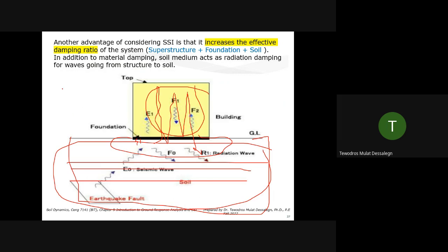And the other thing, actually, the Nuclear Regulatory Commission forces us, because in case there is a resonance in the soil, you can only see it, that resonance, that amplification being introduced into the structure. Sometimes what people do is they analyze the soil alone and use that output directly for the structure. No. You can do that kind of approximation, but it's not realistic.